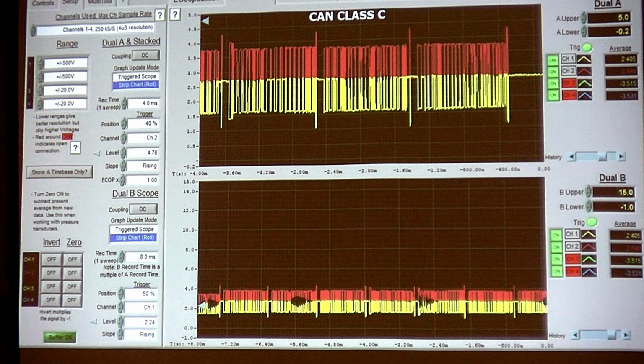When you see some of the high-end cars that have 2 CAN buses, it's because if you have this, you have no way to arbitrate. You can't say how long it's going to take to get control of the bus. Latency would go through the roof, right? So I need 50% idle time at least. So when I get enough messages on the bus to not provide me with 50%, I add another CAN bus. That's why I have multiple buses.